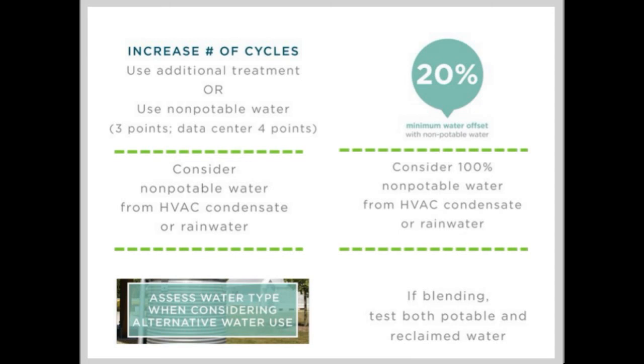Note that acceptable sources should have relatively low levels of dissolved solids. Stormwater runoff from the ground surface or gray water may contain contaminants, including dissolved chlorides, that may need treatment. In contrast, air conditioning condensate and rainwater collected from building roofs have relatively low mineral content.